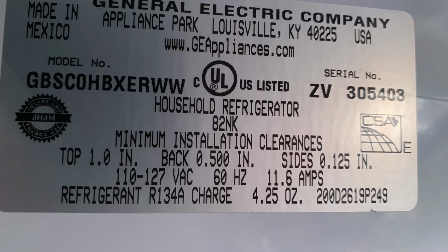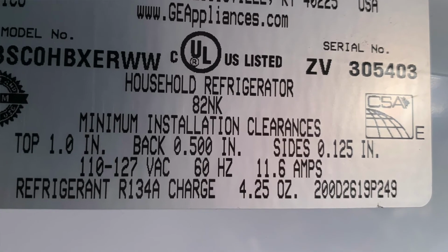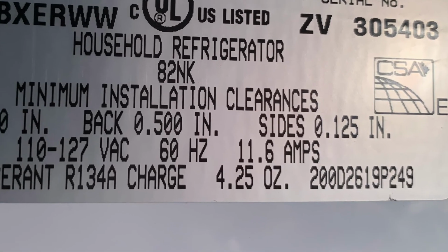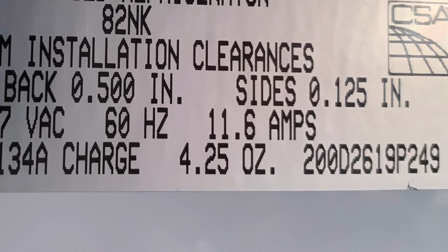You can convert it to kilowatt hours and know pretty well how much that device is costing you. On other devices, they won't have a watt rating. Instead, they'll have an amp rating, or ampere, and that'll be denoted on the sticker or the product labeling as an A. So for example, it might show that it's 120 volts and it's operating at 1.5 amps. That 1.5 amps tells you how much current that device is drawing, again at its full rated load, and you can use that amperage in order to calculate how many watts it's equivalent to.